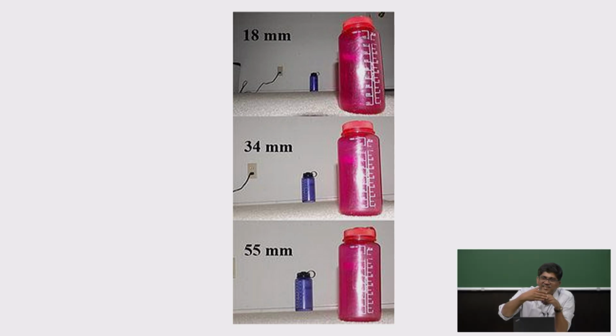Now if I image the entire thing, it depends on what lens I use for the relative sizes between the different planes. Say I illuminate this plane, that plane, and a third plane, and I use an 18 mm lens: this displacement looks very small, whereas that displacement looks very large. With another lens it differs. That's the reason you illuminate a single plane and don't image anything else. Tomographic PIV, again, uses multiple cameras to get that aspect.